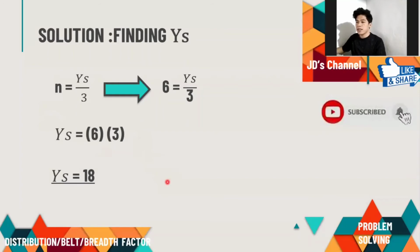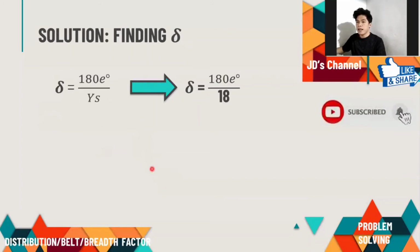So the next one is yung ating delta naman. So delta is equals to 180 electrical degree over Ys. Substitute the value of Ys. So we have 180 electrical degree over 18. So the answer would be 10 electrical degree.